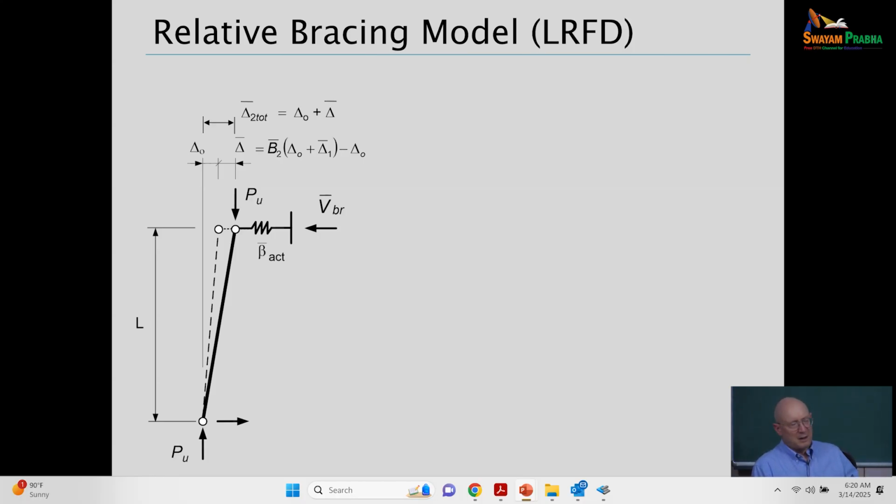In other words, if I put a shear panel, or if I tie it into a truss with a bracing system here, then I'm talking about a shear resistance of that panel that would provide essentially a stiffness to the top. Or if I've got a discrete grounded brace to the top, the way I'm showing it here, either way it's a stiffness delivered or a flexibility of a spring bracing the top of the column. So the derivation's the same. We'll call it a relative brace, but the nodal brace would be the same thing here.